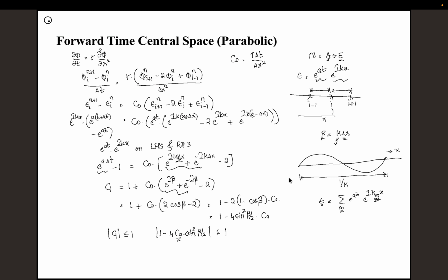From this we will get the values. Here you can see that the gain is a function of my beta and Courant number, where beta has to do with the spatial coordinate grid dimension, and the Courant number is another parameter that we have. So if I can draw a plot between beta and the Courant number, we can get multiple contours, each contour for different values of the g value. If I fix g equal to 1, I'll get this particular contour. You'll see that.